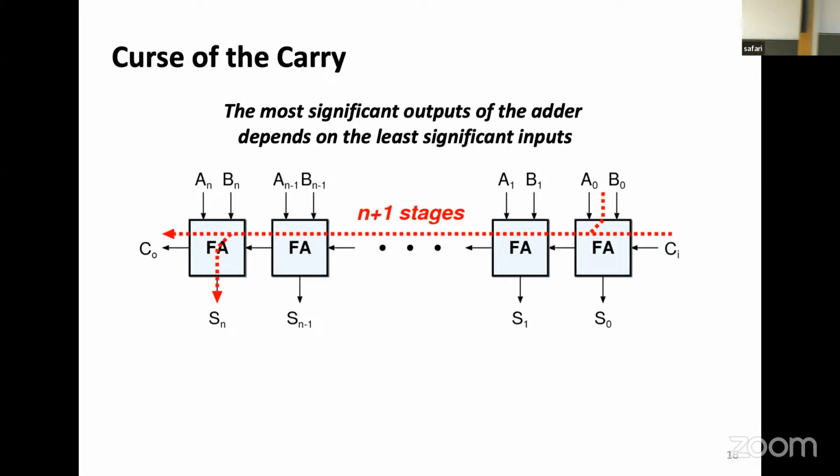Minus 1. If this is 2's complement, we are looking at minus 1. So plus 1 plus minus 1 makes 0. Okay, great. So let's do this binary addition one by one, and you will see what is happening. So first of all, carry in is 0.